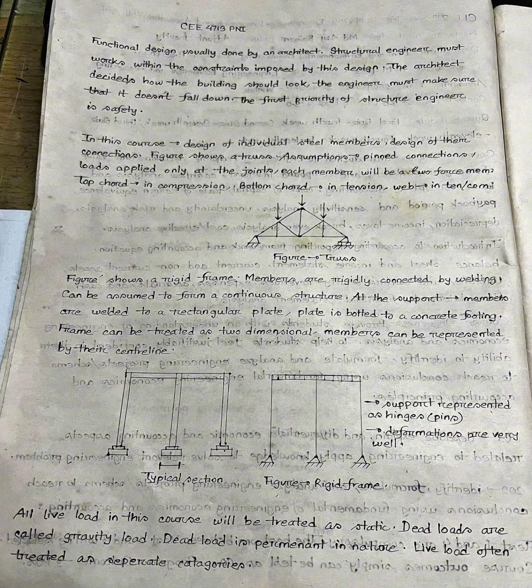Truss design. In this course, the design of individual steel members and the design of their connections. The figure shows a truss. Assumptions: pinned connections, loads applied only at the joints. Each member will be a two-force member.